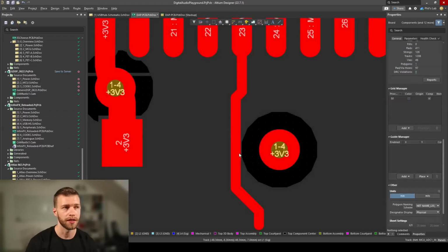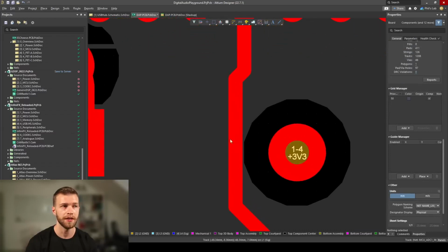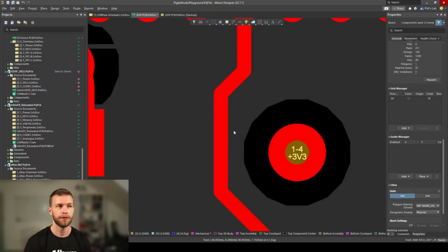For example, like this satisfies the requirement that we need to have a ground plane directly below the trace, but it doesn't satisfy the requirement that we need to have a ground reference either side as well. This is because we have fields between the signal trace and the ground plane below, and the fields don't just appear directly below the trace, but they spread out.